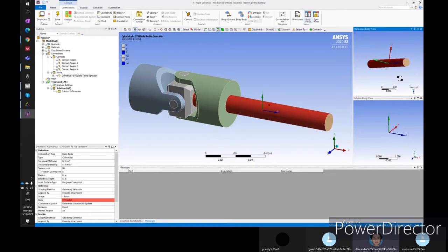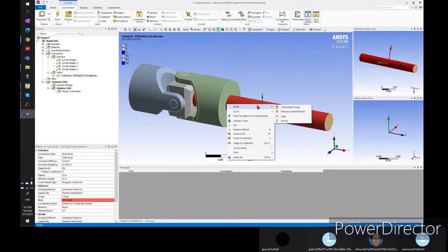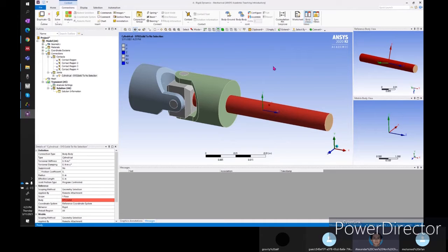So now I selected one face, and this face is going to have a cylindrical relation with the holder. But I can't really select the holder inside, because you can see that I'm not able to select that. You can use select all, or select others, to give you the view. In the latest version it is quite convenient.